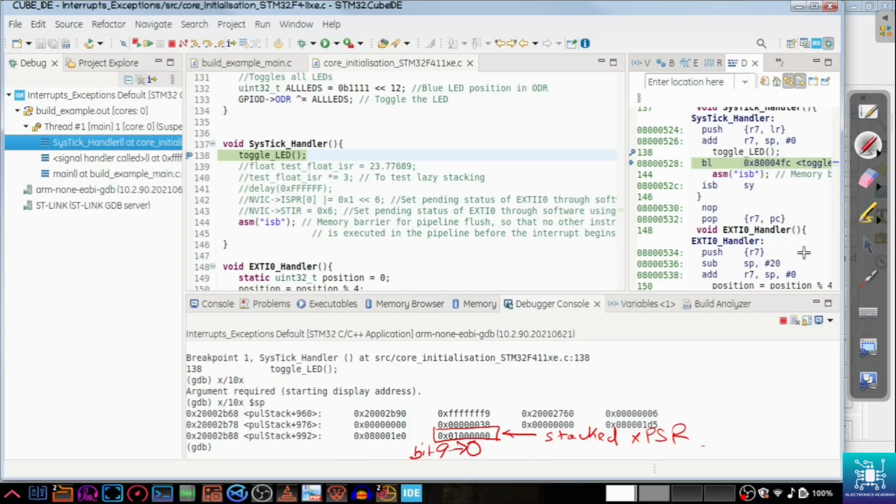So when the stack unwinds and you go back to the previous stack, this value is actually checked by the controller and it knows whether it was padded or not padded. That is how, depending on that, it rolls back the stack pointer that many bytes.